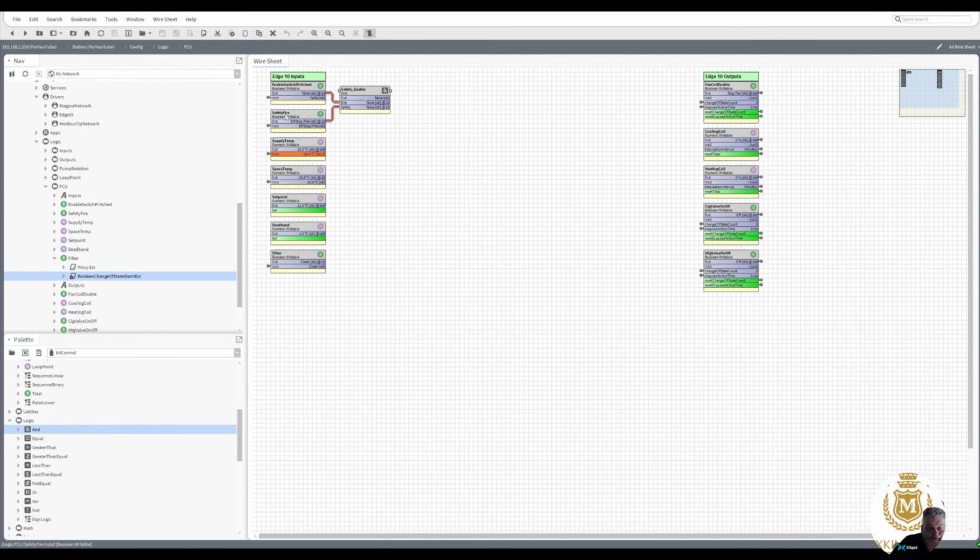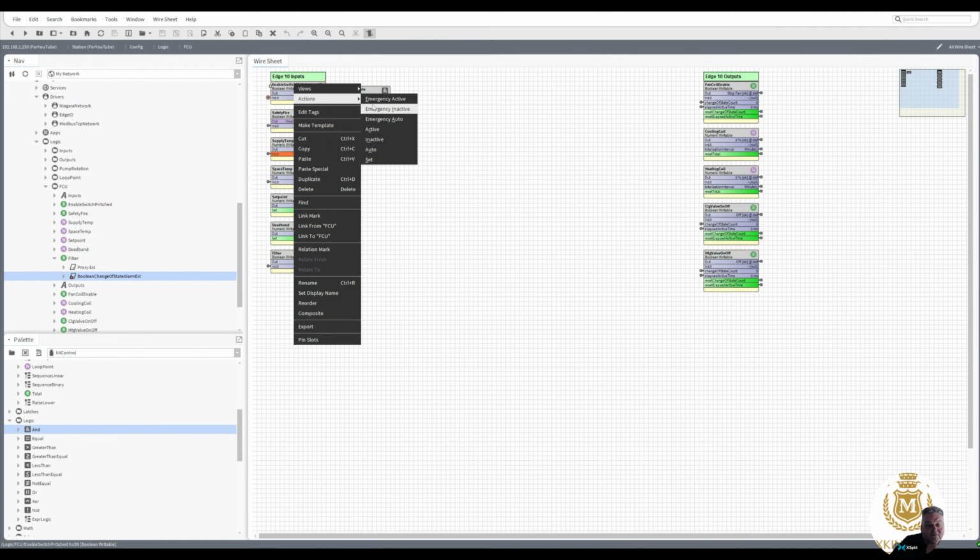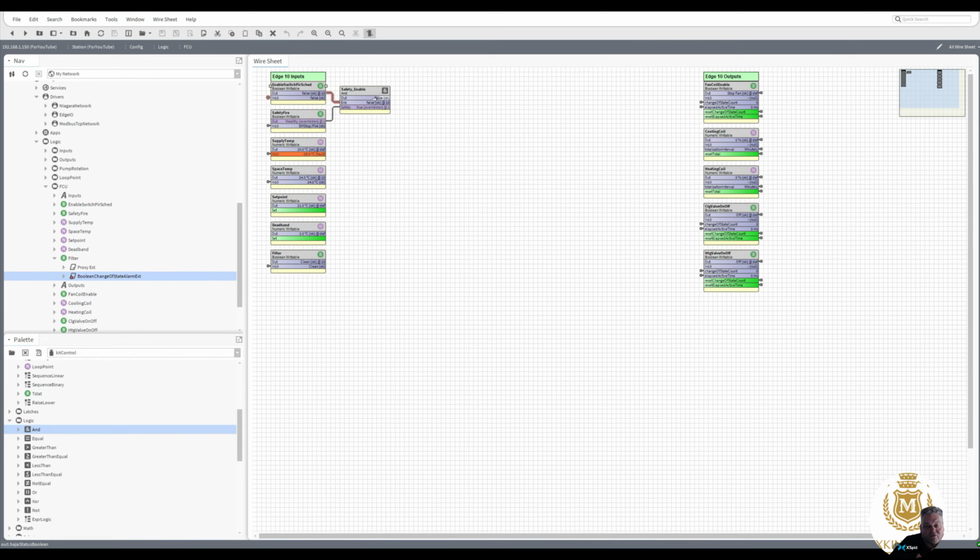So our safety needs to be on. In normal conditions, that is a fail safe, so it's closed between the digital input and ground, and the enable is also either a switch in the room that will be active. So there's my true now. Any one of them go off, we will go to false. So now we're happy to start with conditioning the room. We've got a set point of 21 degrees.